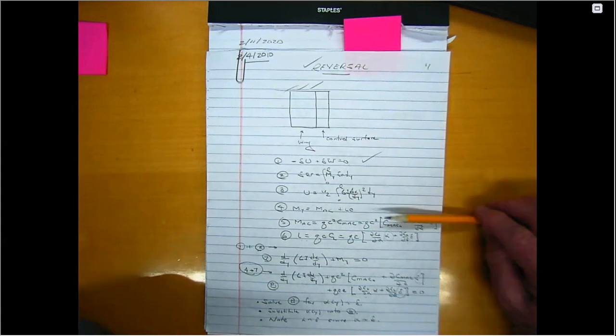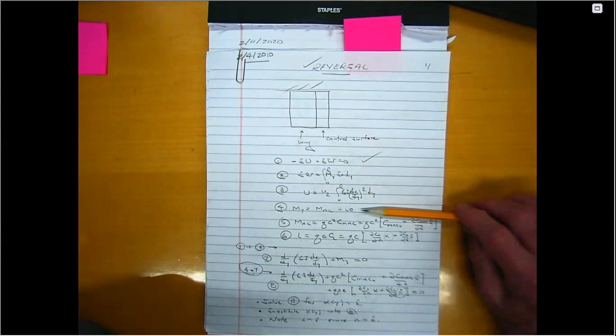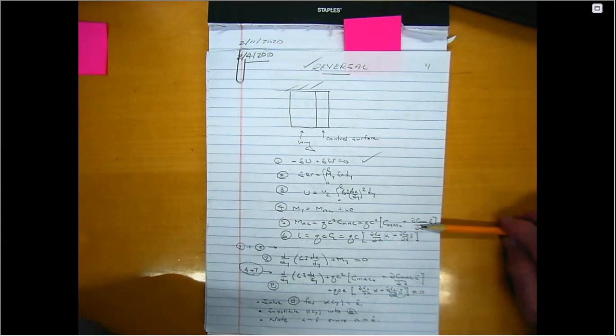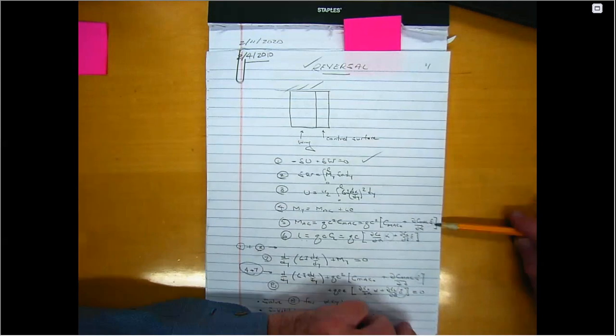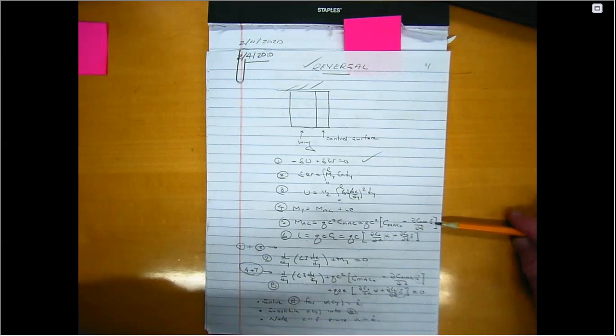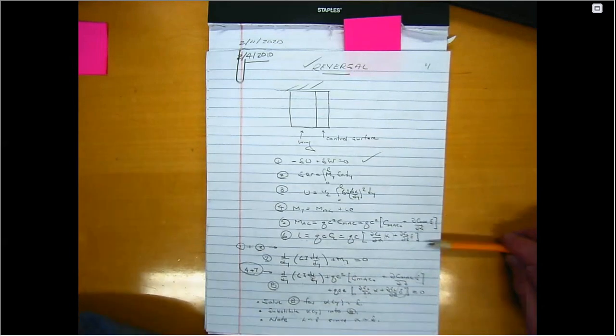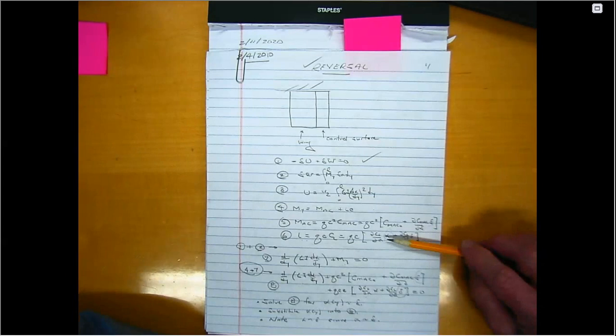We still have the same expression for a moment about the elastic axis in terms of moment about the aerodynamic center, and lift. But now the moment about the aerodynamic center includes a constant term, which I allowed you to set to 0 for simplicity. But it also includes a term that is proportional to delta, because there's a moment about the aerodynamic center once you rotate the control surface. And then, of course, the lift has 2 components. It has a component due to alpha and another component due to delta.